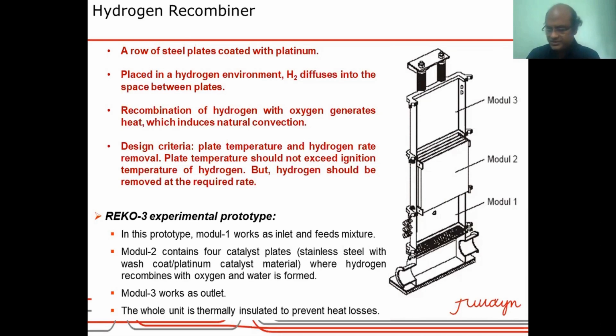If you look at the flame speed, typical hydrogen laminar flame speed in air is 4 meters per second, which is actually 10 times that of methane air flame speed. So compared to natural gas, hydrogen is an order of magnitude more reactive. With hydrogen oxygen, the flame speeds can go to much higher values, like 10 meters per second.